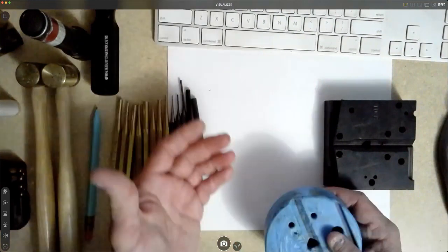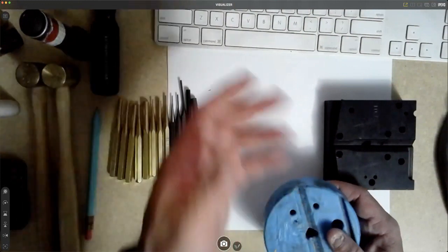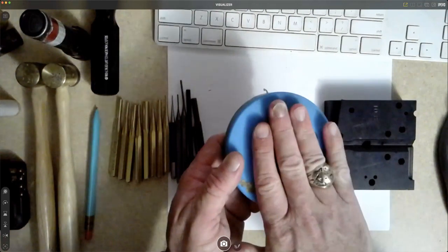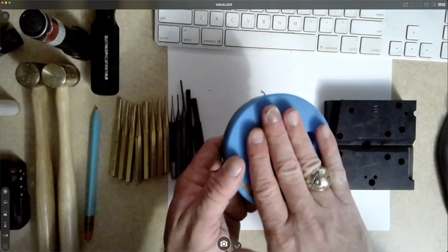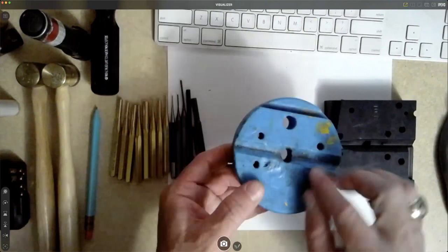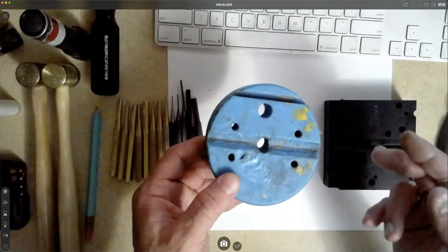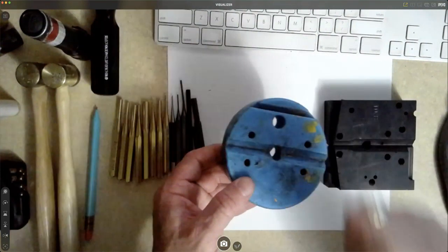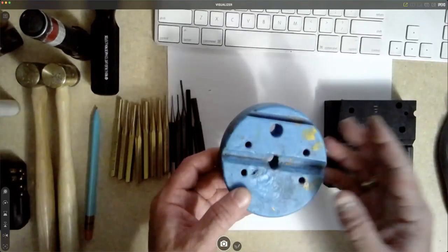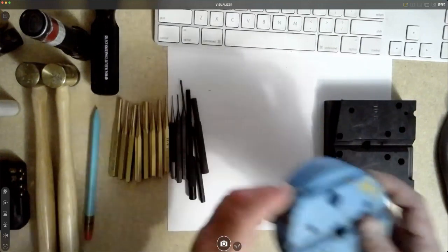There's one for the AR. Look at those different blocks because the AR block, on the backside, has a cutout that supports the standard A1 front sight so that you can drive out those pins. Instead of trying to figure out how to hold it flat, when we only have two hands, holding the pin, the punch and the hammer is not much fun. So always consider buying one specific for the platforms you think you might work on.